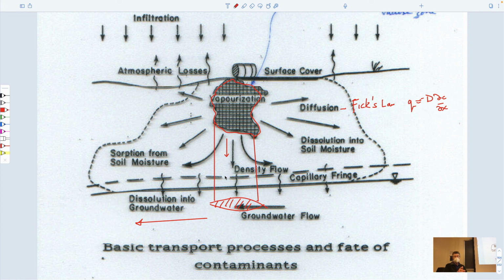So that's kind of the logical progression. Gets into place by accident. Once it's in place, it gets moved around by movement of the water table, dissolution, movement of the water table, and volatilization. We know what those behaviors are for these systems we've looked at as conservative and non-conservative transport in the saturated zone, and conservative and non-conservative transport in the vadose zone. And so now we have a chance of being able to use that knowledge of the motion or lack of motion of these fluids in the subsurface to be able to say, in a mechanistic way, how successful we might be if we try and suck it out, if we try and dissolve it out, if we try and heat it up and vaporize it out. We have the basis to be able to make some value judgments as to how effective each of those mechanisms might be and where they might be applicable in low permeability materials like clays or high permeability materials like sands.